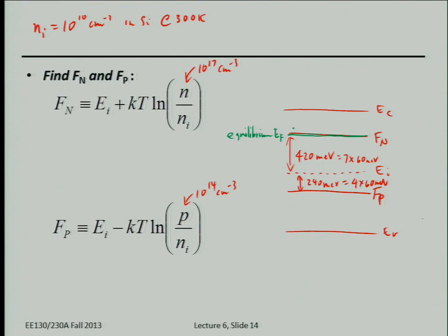Okay, so the question is, yeah, because the equilibrium concentration of electrons is so high that you're not disturbing the concentration. So Fn equals EF. Only if you shine even more light to generate even more electron-hole pairs, more than 10 to the 17 per centimeter cubed, then you start to see the Fermi level for electrons going up, splitting. So you think of it as the Fermi level splitting more and more as you increase. Well, actually, only the minority carrier Fermi level changes. And eventually, when you go to high-level injection, both electron and hole concentrations will change, so both the quasi-Fermi levels will change.